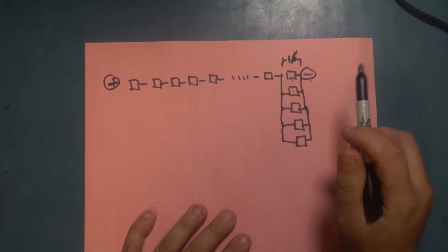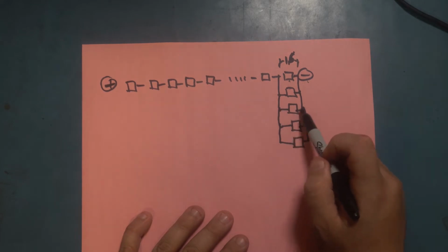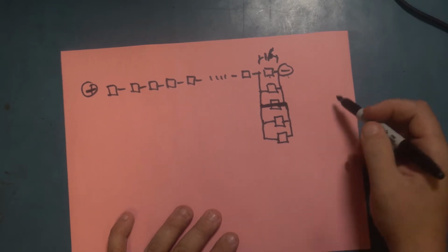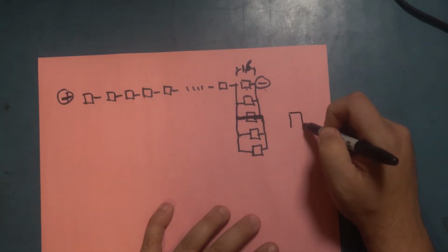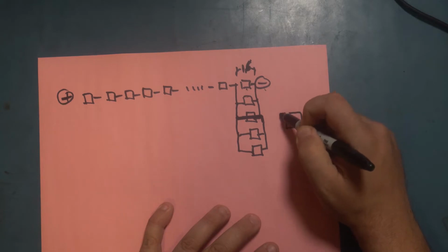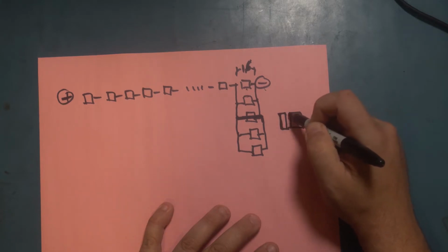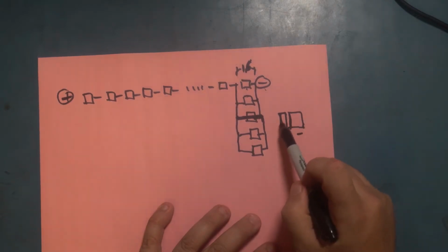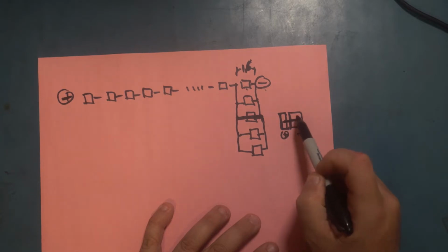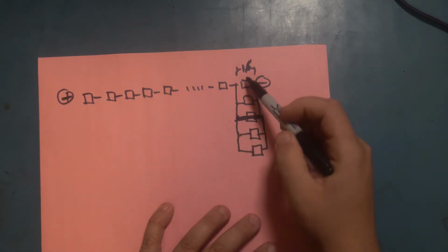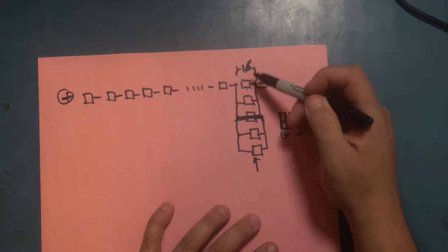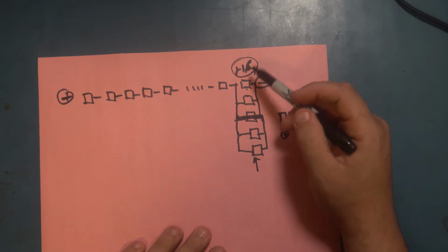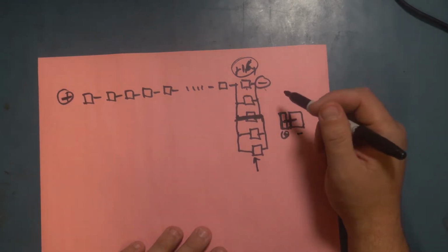And what we got to know and what we got to remember is that if we have one of the chips that is internally shorted between its positive and negative pad, right? So when you remove the chip, you have a big pad as the negative pad, and then a smaller rectangular pad on top. That's your positive. So negative, positive. If through the chip those two get shorted, then that effectively shorts your whole domain. So your whole domain, all those chips, won't have that 1.6 volt as the main supply that they need to get working. So again, something to keep in mind.